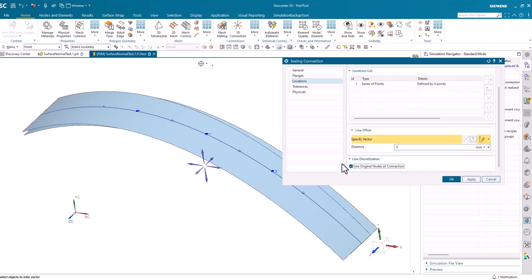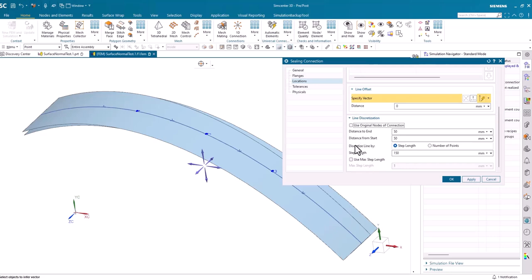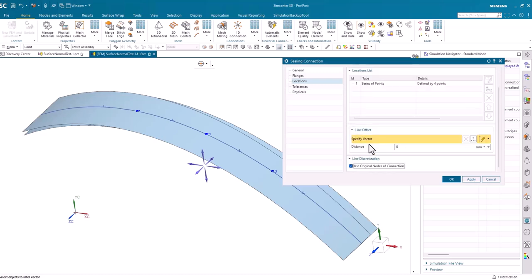And then what that is saying is for my points that I've selected, that's going to be the location for my spring elements. If I wanted to use some kind of discretization approach, I can do that, and I'll do that on a second example using the curve. So okay, now if I update, you'll see these points 1, 2, and 3 will update to my actual selected points.